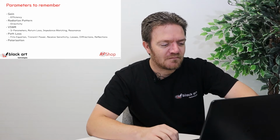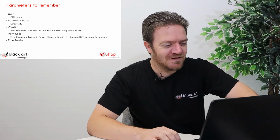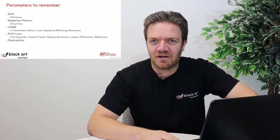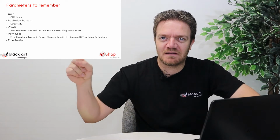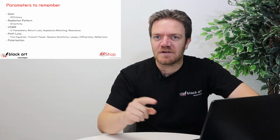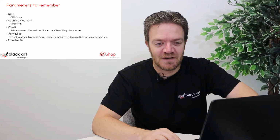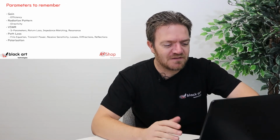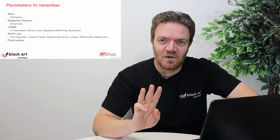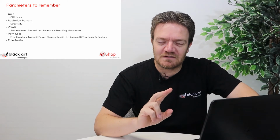Path loss, there's a lot of stuff in there, which is good. I mean, this is where it gets really fun to work on these things. Friis equation. So that's an equation that you can use to calculate how much power is at a certain distance. So I send X amount of power. How much power do I have at my receiver? So you use this Friis equation to get to that. Transmit power, receive sensitivity, losses. Those three terms are used in the Friis equation as well, so that they can be used to figure out how much do you get.